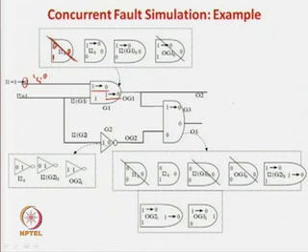Now there was another gate, I2 stuck at 0. This corresponds to the second gate in this list. If you remember, this I2 stuck at 0 was a stuck-at-0 over here. So this input was a 0 because this gate is stuck at 0. Now there is an impact of the change from 1 to 0, and the answer is of course a 0, but this gate will be retained. Why will this gate be retained? Because initially it was 1 0 and the answer was a 0.